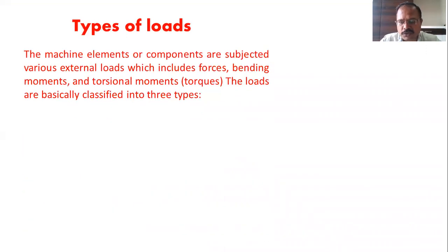Starting with different types of loads. Basically, there are three types of loads which are used for the designing. But when we are talking about a load, we mean the forces which the machine component will be subjected to. We mean the bending moments to which the machine component will be subjected to. And we mean about the torques to which the machine component will be subjected to. That means the load is a broad term which includes forces, bending moments, and the torsional moments or torques.